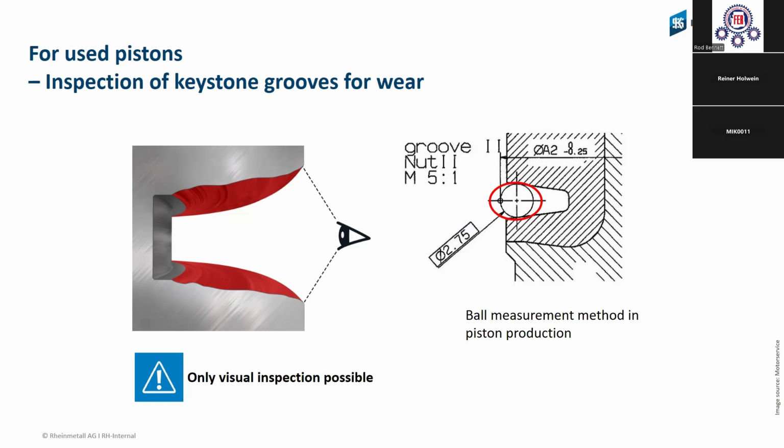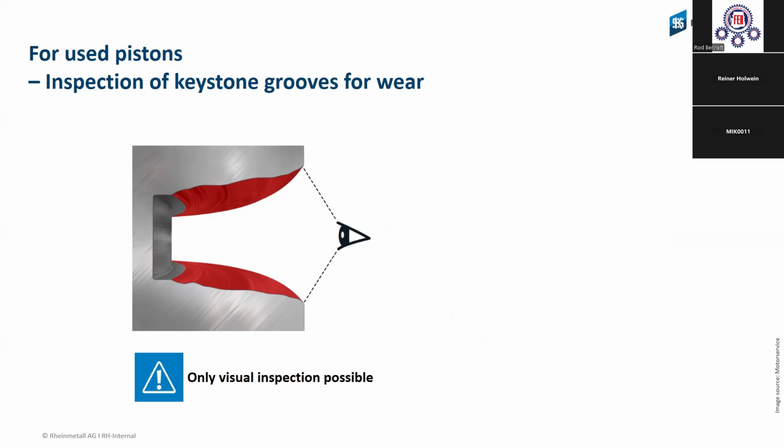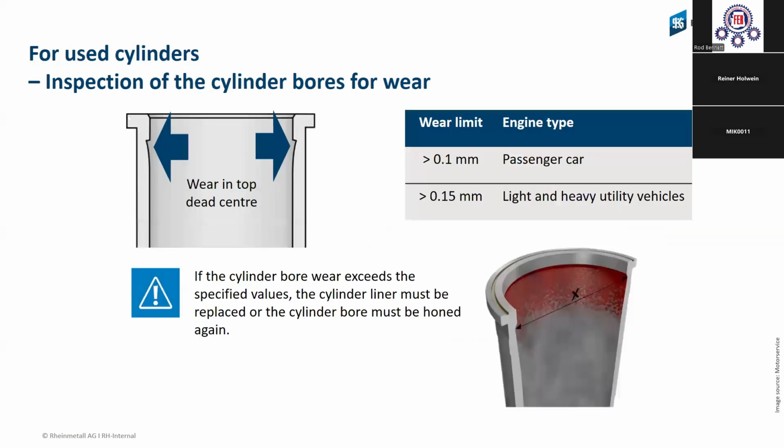On the right side, you see, we have a special bolt. Each piston ring is different in diameter and in height, so we have a special bolt for each ring. We pull this bolt inside, and then we measure how far the bolt stays out of the surface of the piston. And then we see whether this area, this angle, is correct or not. But you can only do it physically, with your eyes.